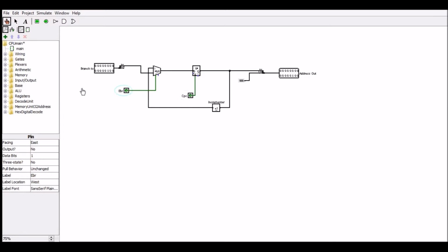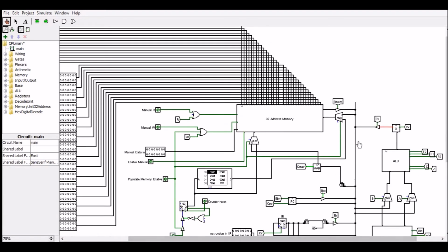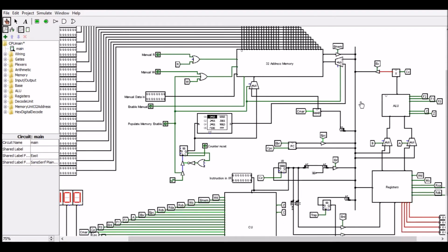It's worth noting that throughout the CPU, in order for data to travel onto the bus, we'll go back to the main bus, it has to be 16-bit because that is the largest data that has to travel along the bus. Components in Logisim connected to each other have to have the same input and output width, even if the tri-state gates aren't enabled, so they're not directly interfering with each other.